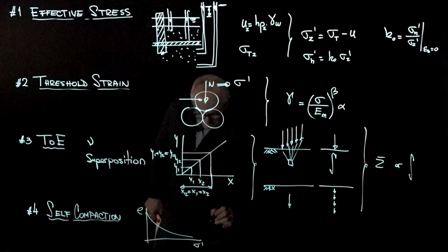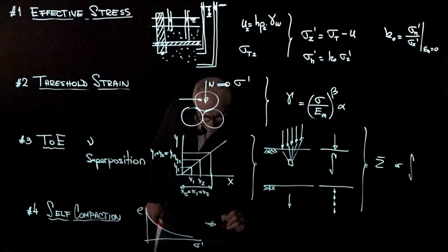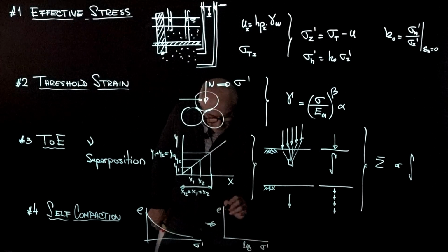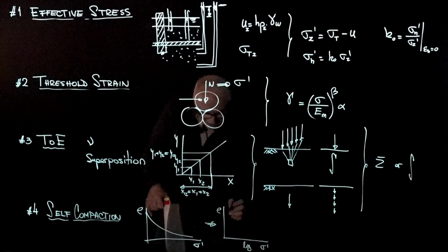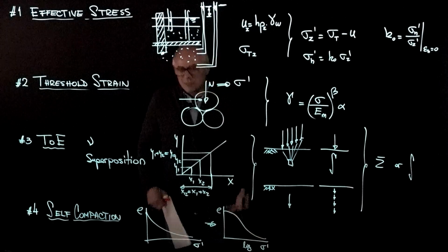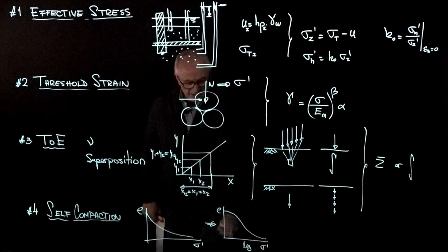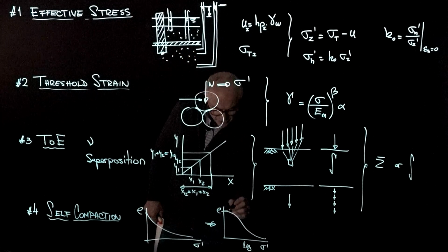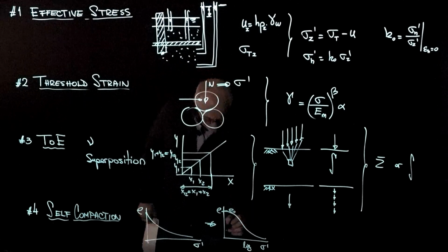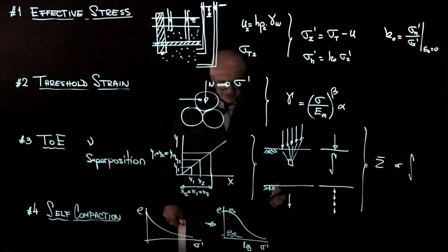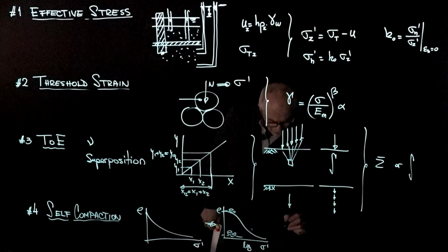What happens is that we plot this one in semi-log scale. So by the time we plot in logarithmic scale of sigma, we stretch the origin and we contract the long tail, and this deforms like that. But don't be misled. This is really an exponentially decaying function, and there are asymptotic values. This is the void ratio at zero effective stress, and this would be the void ratio as the effective stress goes to infinity. And so I can write equations of the following form.